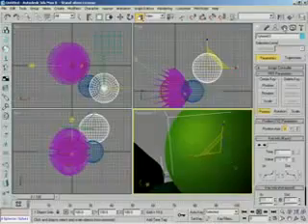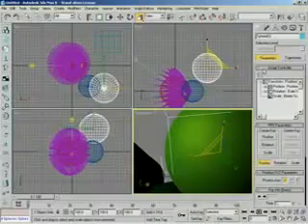Ooh. So it's really the control of anything that can be manipulated over time. Because when you start getting into assigned controllers, we could get into some pretty fancy stuff in here. Yeah, a whole new world opens up. It really is. This is where we start throwing in controllers, and we're basically telling 3ds Max, okay, in regards to the motion, in regards to the translation of this sphere, we're going to control it with a noise controller, okay?